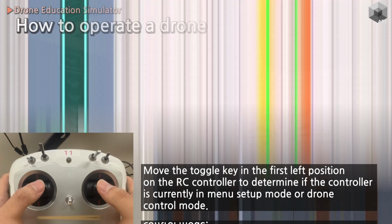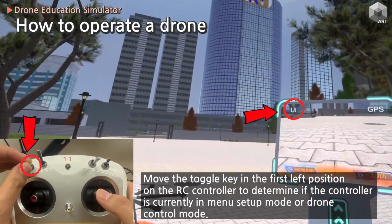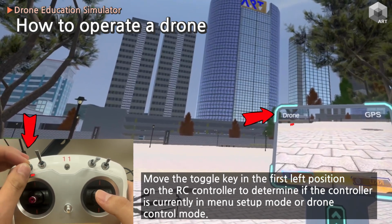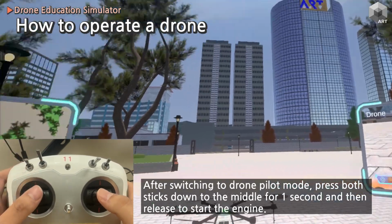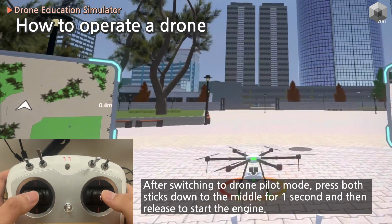Next, I will explain how to operate the drone. Move the toggle key in the first left position on the RC controller to determine if the controller is currently in menu setup mode or drone control mode. After switching to drone pilot mode, press both sticks down to the middle for 1 second and then release to start the engine.